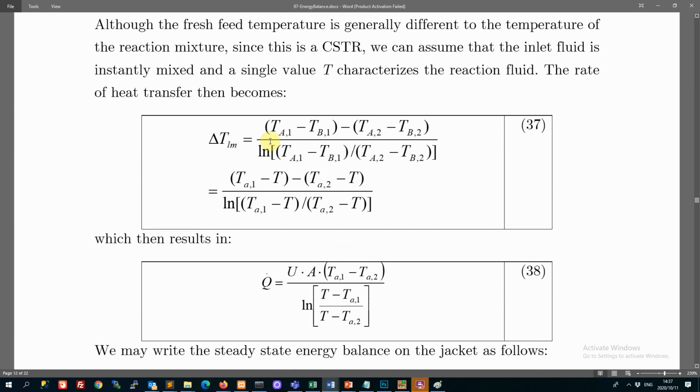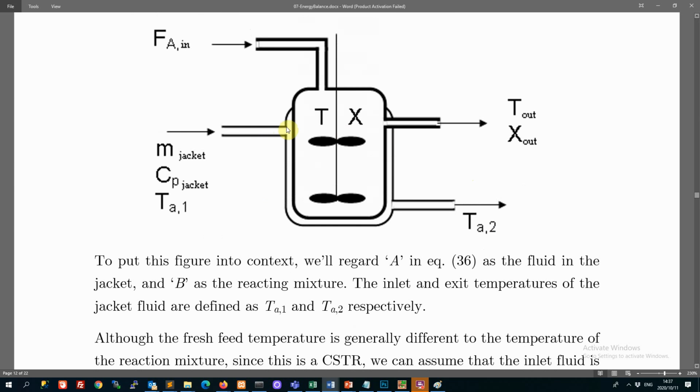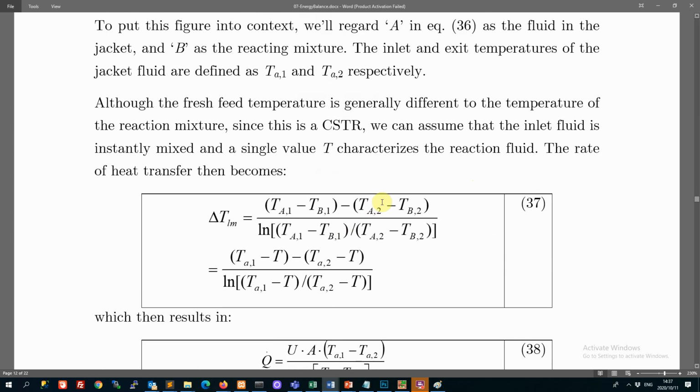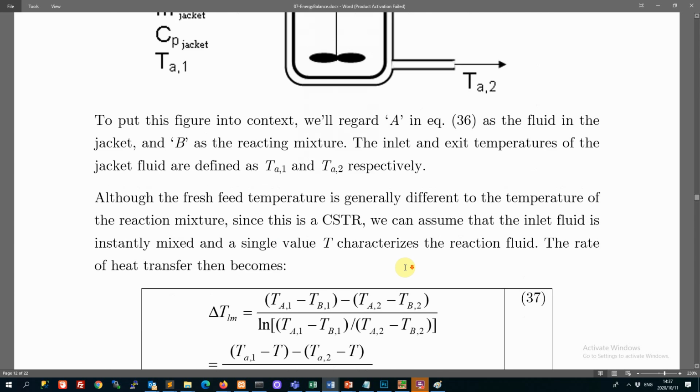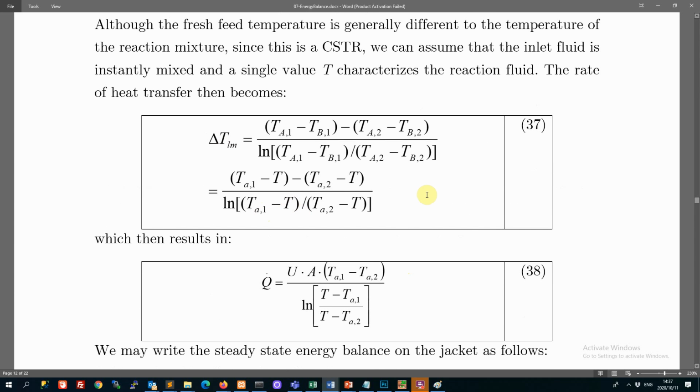But we are applying the same definition for log mean temperature difference. So this is again an engineering feature: even though we really should go and rederive this whole thing for this other weird flow pattern we've got going on, we don't do that. We just say, oh, close enough, let's try this out. And we actually find in most situations this is very close. There's hardly any difference, and even though the flow is not quite the same, we just go ahead and accept it.